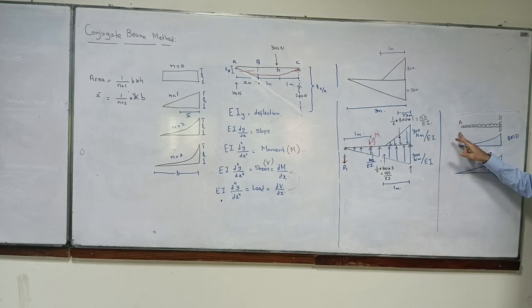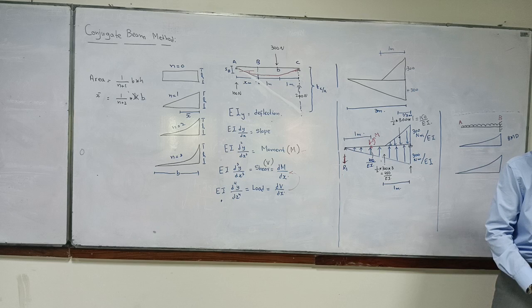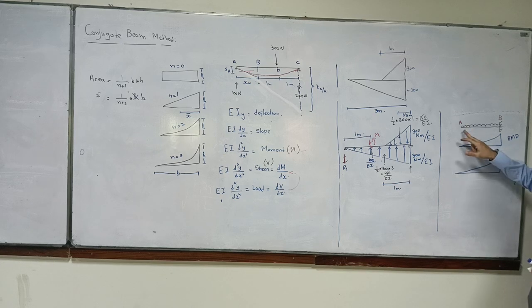At point A is free, so my slope is finite. Sorry, my deflection is finite. I would have a finite deflection and finite slope at A, isn't it? Yes, sir. So what does that mean? But in reality, in the given case, my A is free. So the shear and moment are...